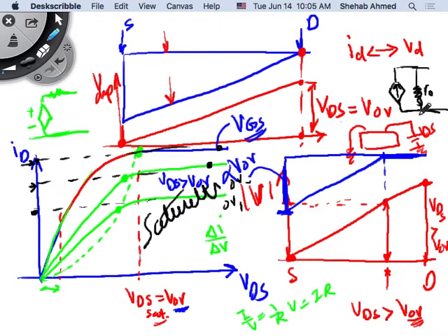That is wonderful. I can control it depending on my input. Now this is my output side. My input is what? My gate voltage, VGS. Right? So I have an input that is voltage, infinite input impedance. I'm not drawing any current. Am I drawing any current at the gate? It's a capacitor. I'm not drawing any current. So I'm just adding voltage.